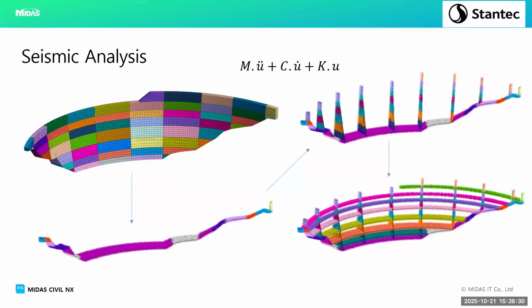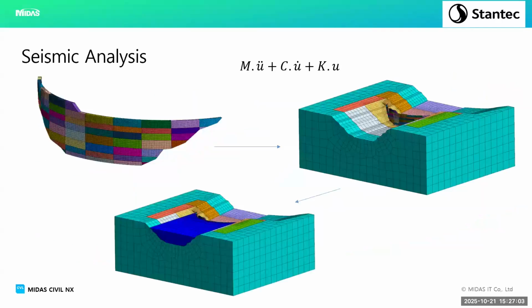So it looks like quite a complex model, which it is. Advertising for you guys, what I found good with MIDAS is it's got a very powerful automesher compared to other software I've used. The key is making sure your geometry is done correctly, taking the time. I'll stress that with any FEA: getting the geometry right in the beginning is very key to saving time throughout the entire process. If you do that right, you're pretty good to go.